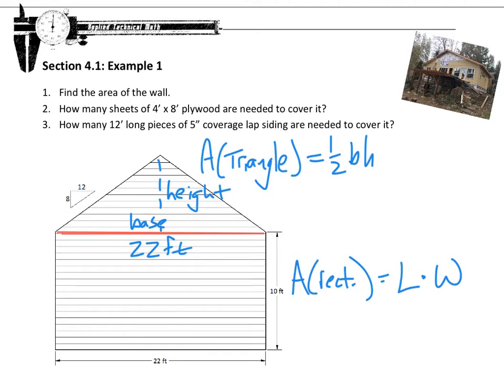My roof over here is a slope of 5/12. But we can find this out now. See this little triangle here? That's a rise and a run. So we need a rise. The rise is the height, and the run would be this distance, which is 1/2 of 22. So this is 11 feet. And so we've got to make a proportion to find the height. 8 is to 12. That's the slope. As the height, which we don't know, this rise, is to this run, is to 11.